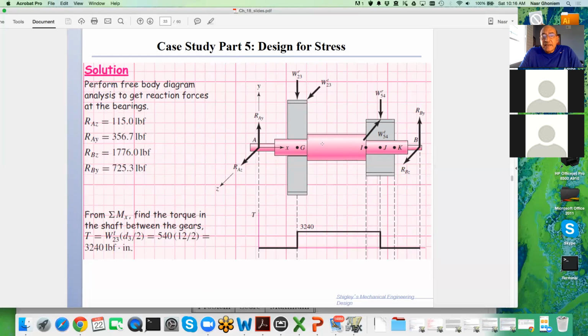And the statics, meaning what are the forces on the reactions. Luckily, we don't have any indeterminate systems, so it's all determinate, very easy. So you take the moments about this point, and then you have vertical, horizontal equilibrium. You get the 4 reactions at the two ends at A and B.